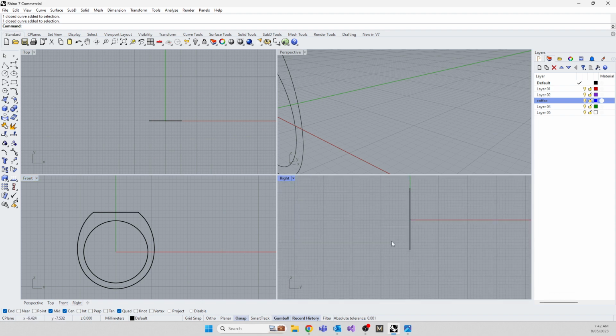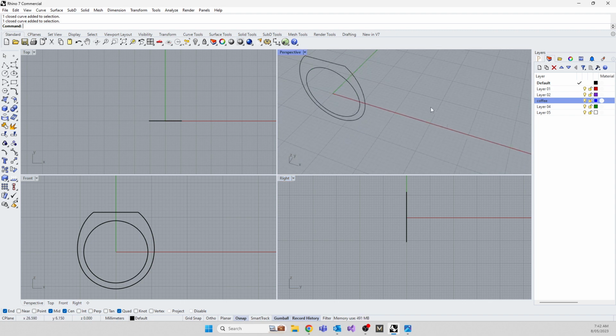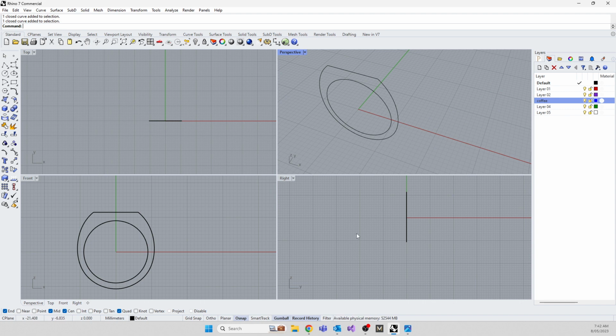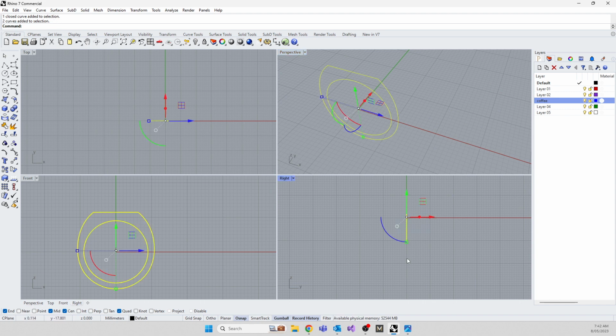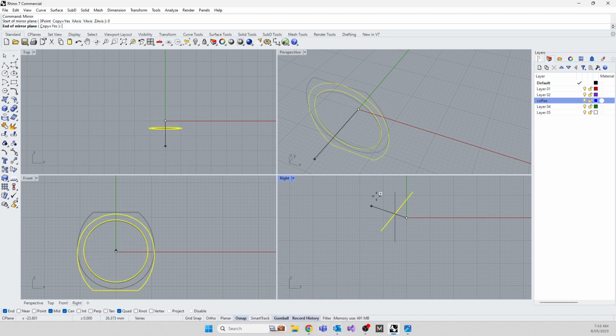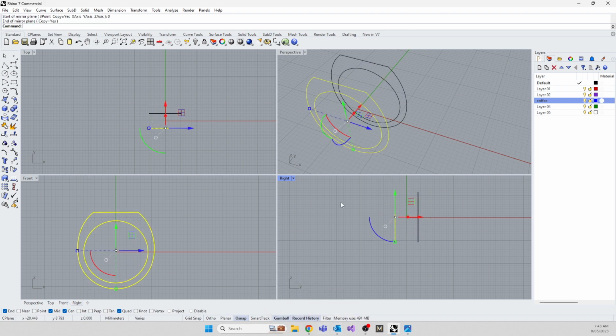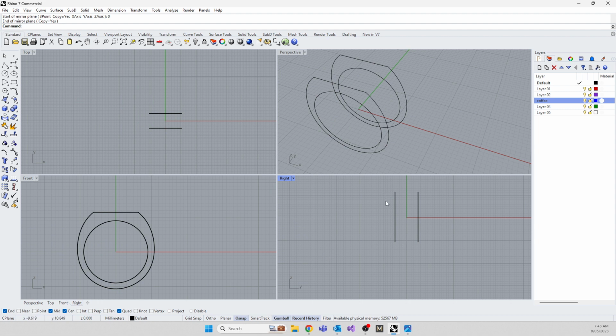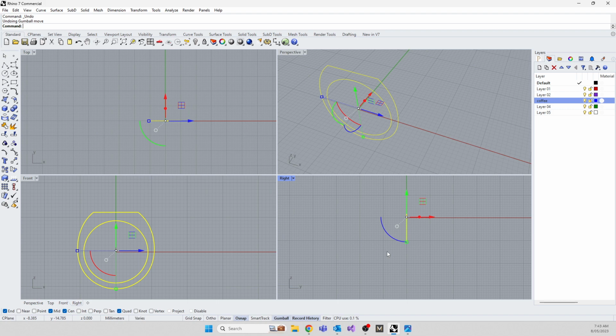What I want to make is a ring, like a gents ring, that comes tapered down and has a flat on the top that we can put a pattern onto. There are 2 different ways to do this. You can extrude it and you can taper it, which is a fun tool. So we're going to do that for today. The other way you could have done this is mirror this over to the other side, and then bring your points into each other, and then do a loft. We're going to do it a fun way. Nice little fun tool for you to play with today.